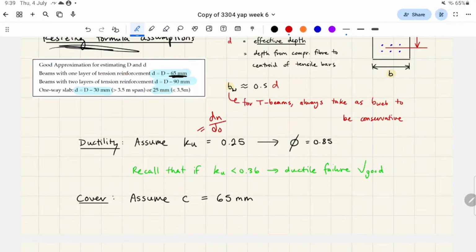Yes. So if our ratio of DN to DO is too high, it means that the concrete is going to reach ultimate compressive strain before the steel yields, which isn't good. It's not about concrete cracking. Because if the steel yields first, right, that's what we call a ductile failure, right? It's really hard to explain this concept because there's not really another analogy that I could think of.